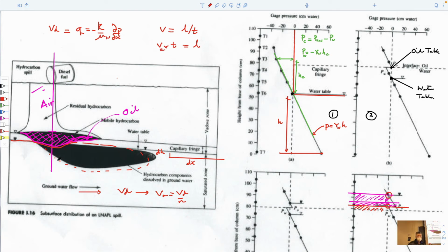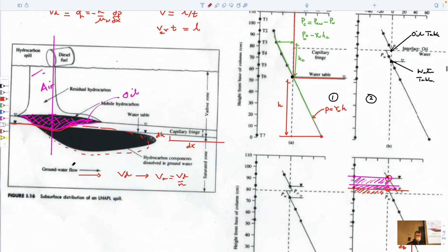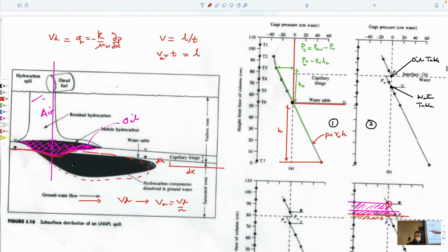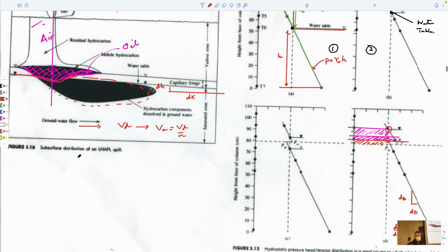And this would be the advective velocity. So you've already done something like this. So you can do something useful already. If for some reason a portion of this groundwater only zone was partly filled with NAPL, then we'd perhaps have to use a relative permeability in this to be able to represent that. That should be easy enough for us to do as well. So that's maybe what we need to know about gasoline escaping from underground storage tanks and what it might look like in the subsurface. And of course this says something about the architecture.